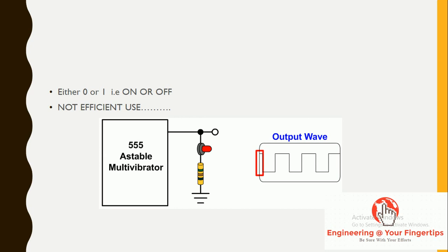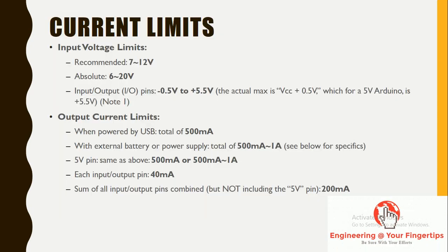One thing to be aware of when you are actuating something, especially in this power mode, is to think about the current limits of both devices. Your microcontroller and your actuator can have different current limits, and this can cause problems for your IoT devices. For instance, a typical LED might only be able to handle 20 milliamperes, so you can't drive it with more than 20 milliamperes without hurting it.